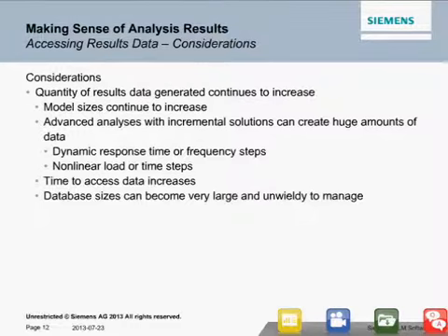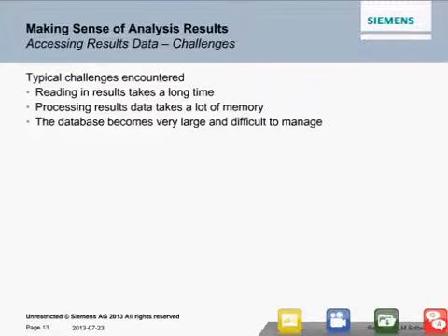So in terms of typical challenges that these present, reading in results data, if it's a lot of data, reading it in is going to take a long time. When you come to process, doing all the post-processing in a product like FEMAP, that is going to itself take up some computer resource. It's going to take up some memory. And as I mentioned just now, the database files themselves can become very large and unwieldy to manage.